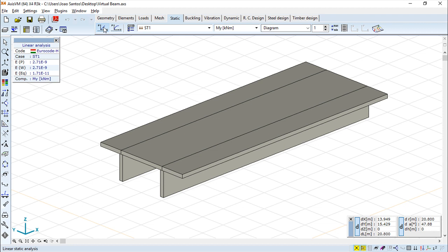All the load cases are solved with this analysis, and through the geometric linearity, it is assumed that the displacements remain within the limits of the small displacement theory. This means that we are working in an area that is called the linear elastic area. So this is where we play when we work with linear analysis.